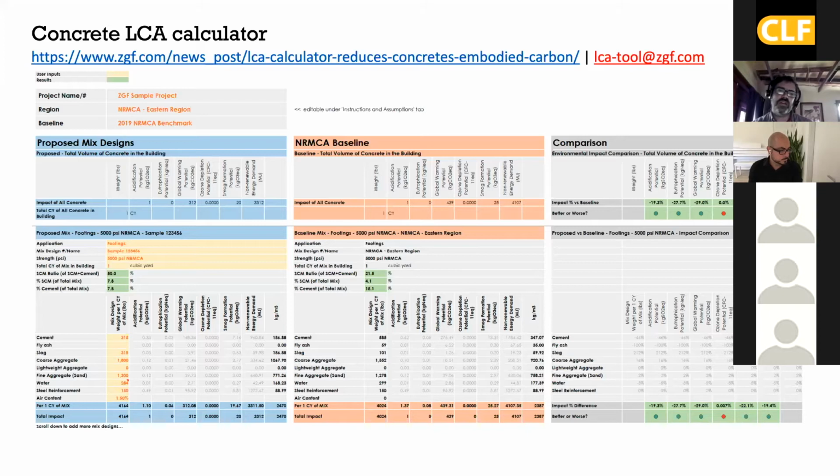We've seen numerous benefits on projects now. A lot of times people are doing shorthand, you know, percent SCMs or supplementary cementitious materials. And we found at least one situation where we asked for more SCMs and the supplier came back and gave us more fly ash and slag, but didn't actually reduce the cement content. So the percent SCMs increased, but the global warming potential of that mix actually increased versus decreased. So this tool was more of a neutral playing field. We could make a relative comparison for any one supplier to find better mixes and align it with the data that's coming out of Tally.